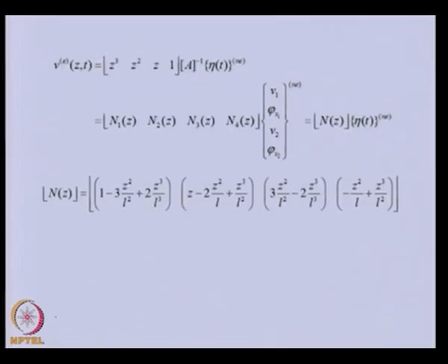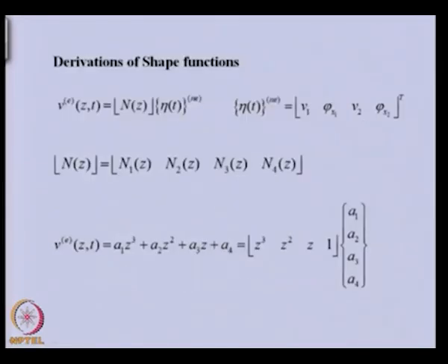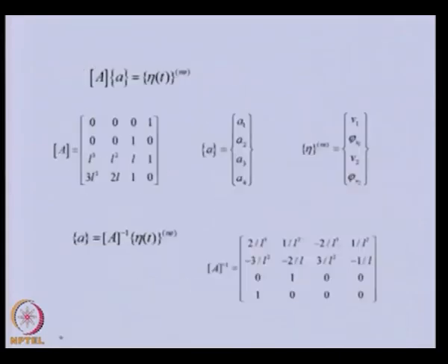of the polynomial. Now, we earlier expressed this particular displacement, the shape function displacement, like this. Basically, we had a here, which we have now obtained as A inverse into eta. So, we are substituting this quantity in place of a in this expression.